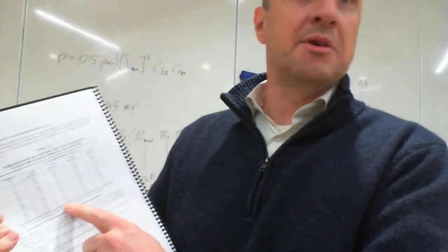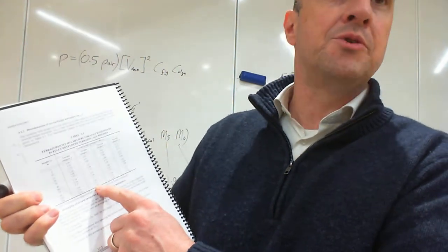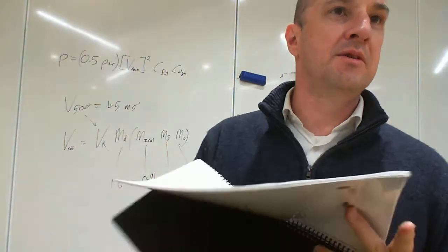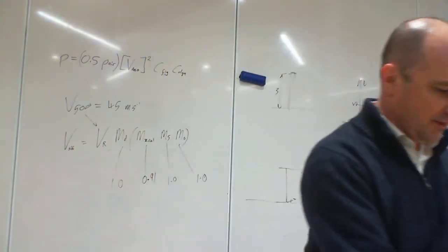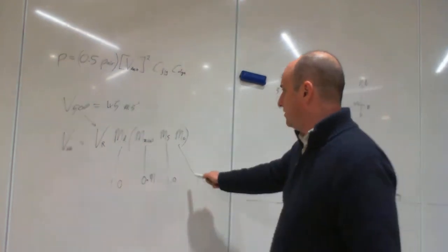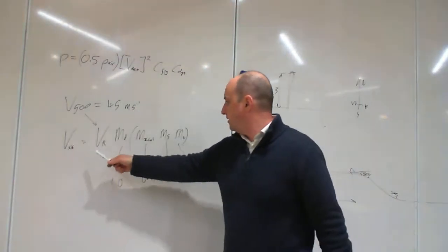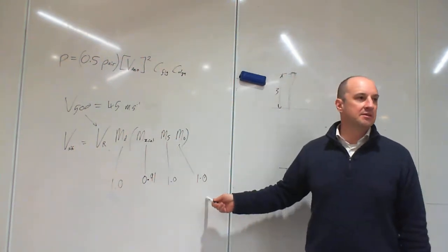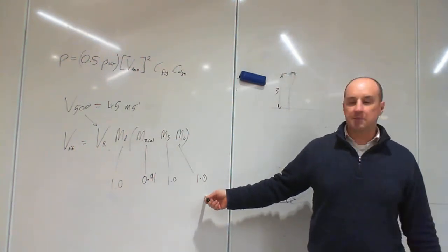By the time you get to something that's 200 meters tall, you've got 1.29. So you've got a 30% increase in wind speed by going higher. All right. Tall things get blown more. All right, so we have now our wind speed and our 4 categories. Sorry, 1.0, if it's flat ground, less than slope of about 1 in 20, 1.0.